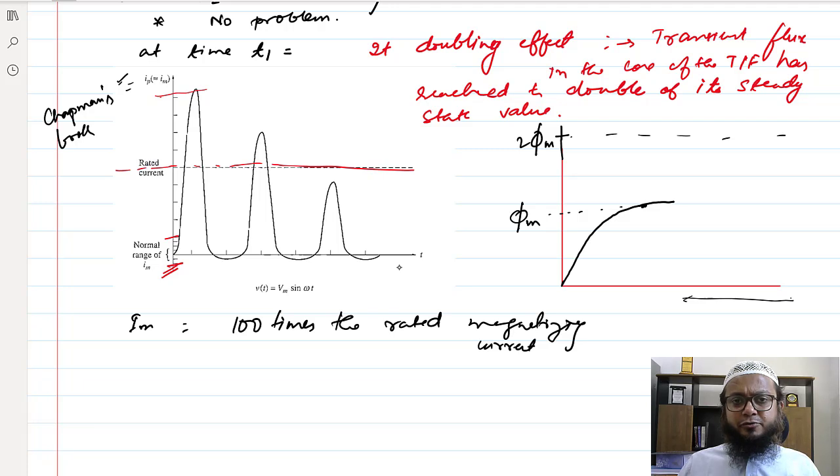And we have also talked about auto transformers, voltage regulation, and then parallel operation of the transformers. And then three-phase transformers, various connections of it, Scott connections, and special connections like zigzag connections. We have discussed all of it. And then we talked about one important aspect, which is the harmonic problem in three-phase transformers, basically star-star connected transformers. To mitigate it, we can use either a tertiary winding, or we can use a neutral. The neutral of that star point should be grounded. And then we talked about the switching transients as well.